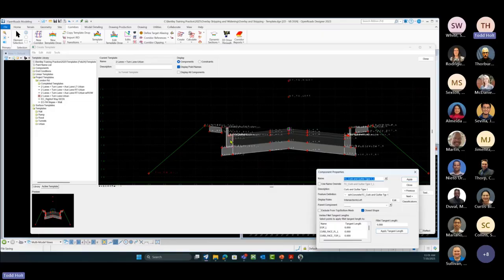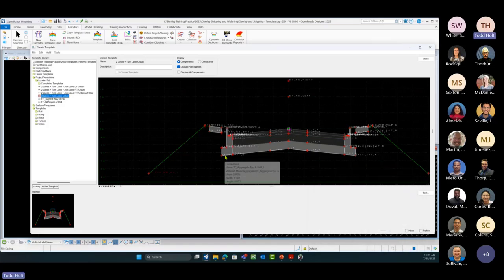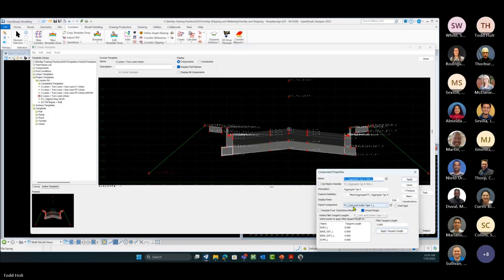This component is going to be a parent of all these other components. So when this turns off, it's going to turn all these off. If I look at this component here, the parent component in the group is this curb. So it's going to keep these all together to turn off or on. If I don't want it to display in a certain area, I can use that parent component relationship to turn everything off in one area by applying this trigger, this switch, to that particular area.